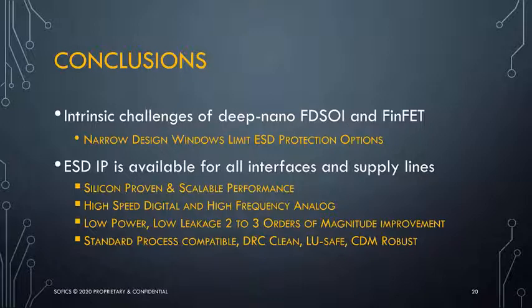I've also demonstrated low-power, low-leakage solutions, 2 to 3 orders of magnitude improvement over the PDK, and this over the full temperature range that we have for our devices. Finally, we have standard process compatible solutions, DRC clean, latch-up safe, and CDM robust.